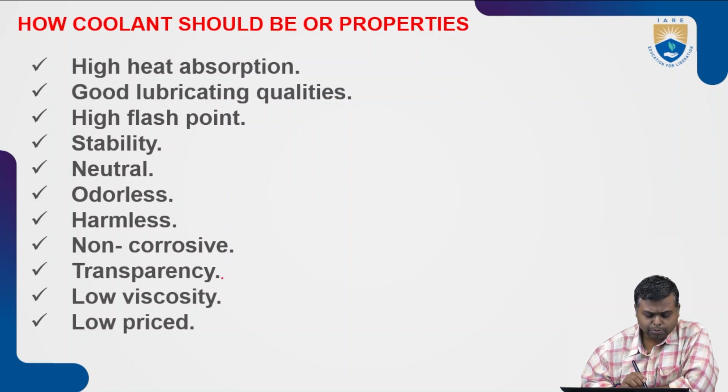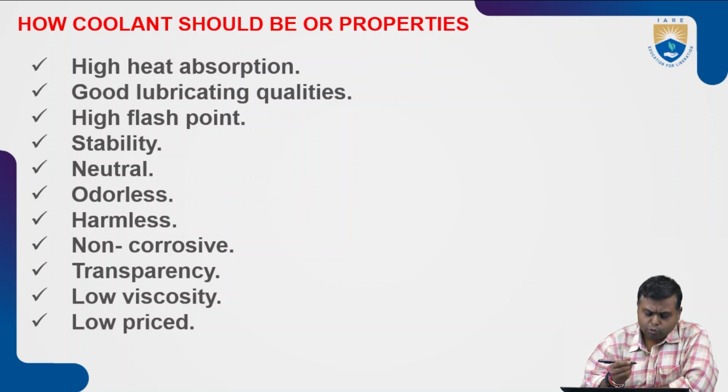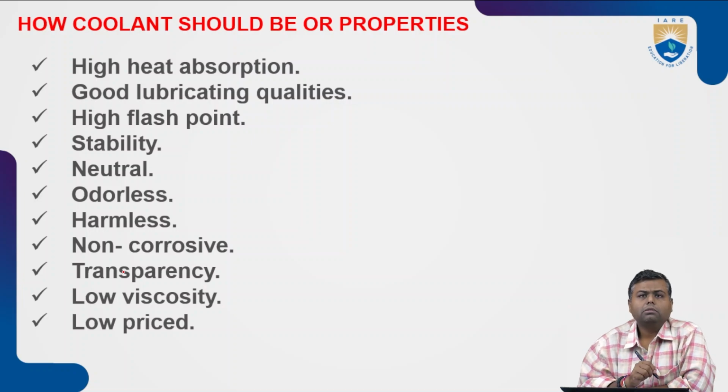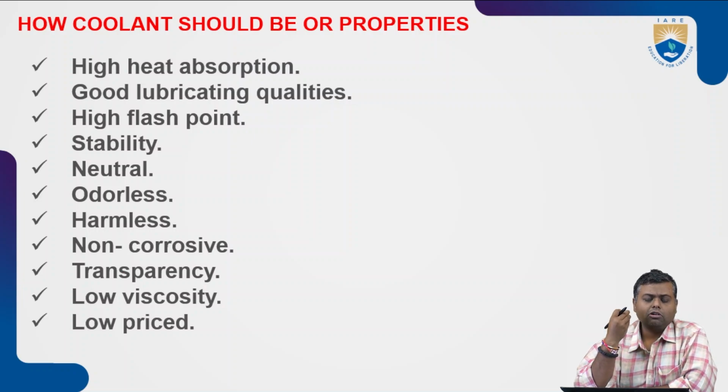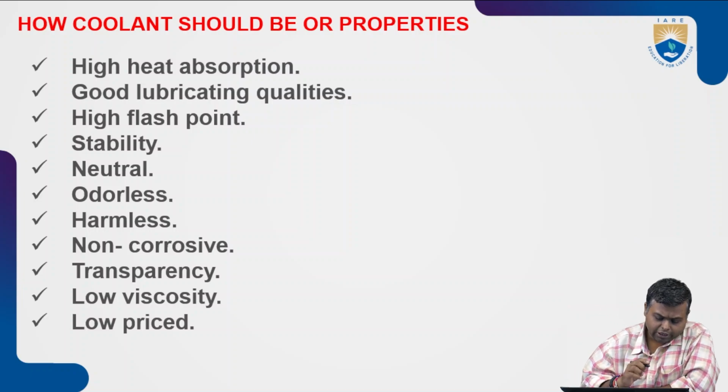Then it should be transparent. Adding color will disturb the machining process. There should not be any disturbance in terms of the machining process. If you use a colored type of coolant, the machining process cannot be visualized, so it will be a blind spot. But if you use a transparent kind of fluid, we can observe the cutting process very clearly.